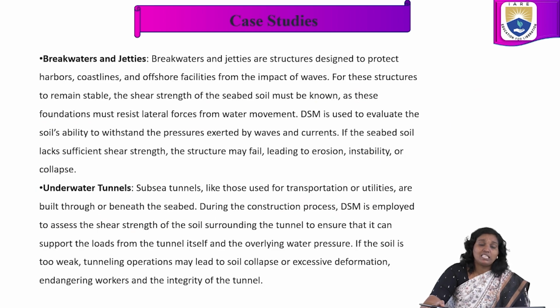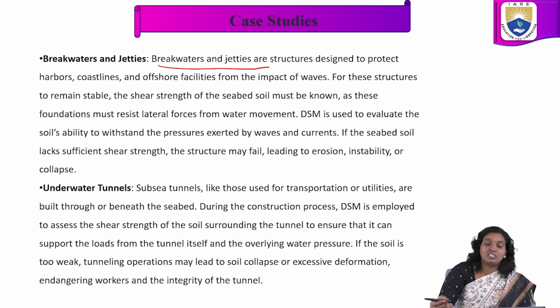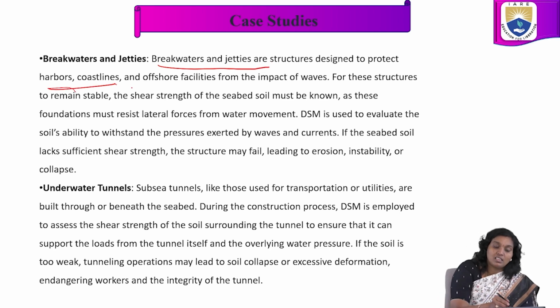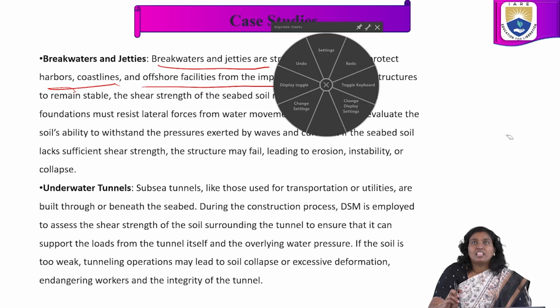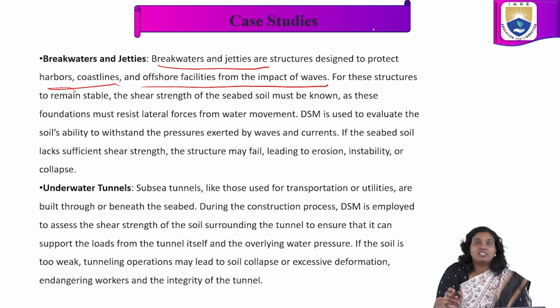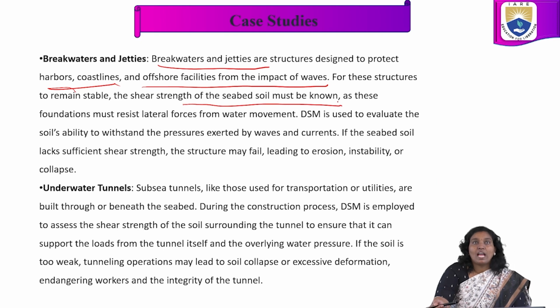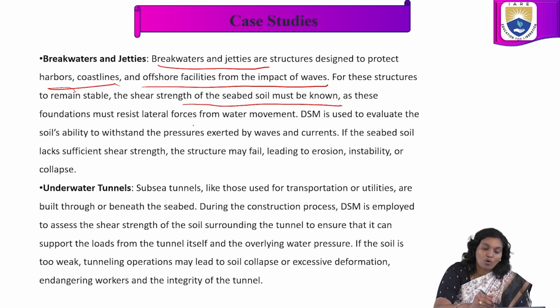Breakwaters and jetties are structures designed to protect harbors, coastlines and offshore facilities from the impact of waves. For these structures to remain stable, the shear strength of the seabed soil must be known, as these foundations must resist lateral forces from water movement.